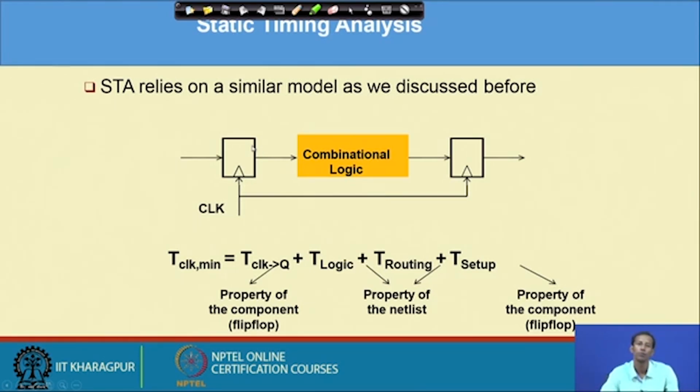If you remember the internal structure of flip flops, there are 4 NAND gates. That means the clock has to pass through 2 levels of NAND gates, so the flip flop itself has some delay in propagating the clock to the output. That delay is mentioned over here.